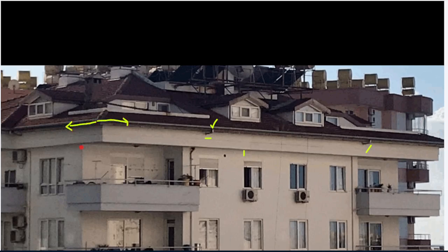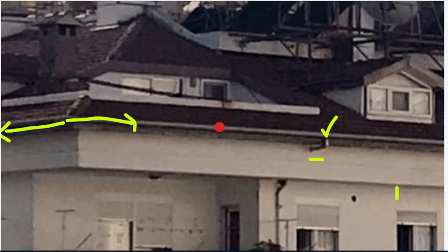My suggestion is to put 3% of slope, not 1.5. And the reason is that the faster you manage to take the water down the pipe, the easier it will be for you, and this place will not be dirty in the future.